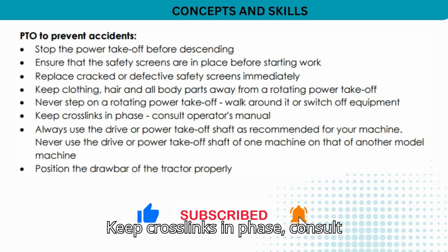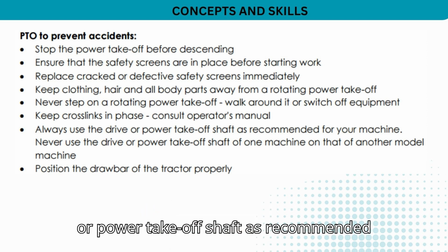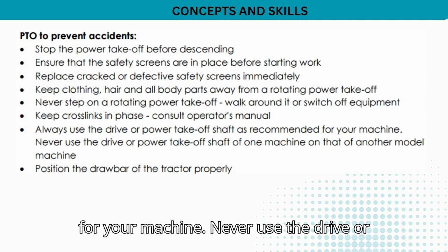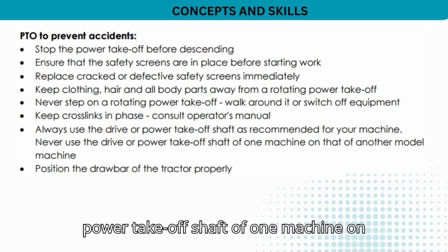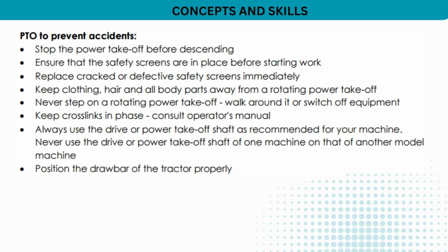Keep crosslinks in phase, consult the operator's manual. Always use the drive or power takeoff shaft as recommended for your machine. Never use the drive or power takeoff shaft of one machine on that of another model machine. Position the drawbar of the tractor properly.